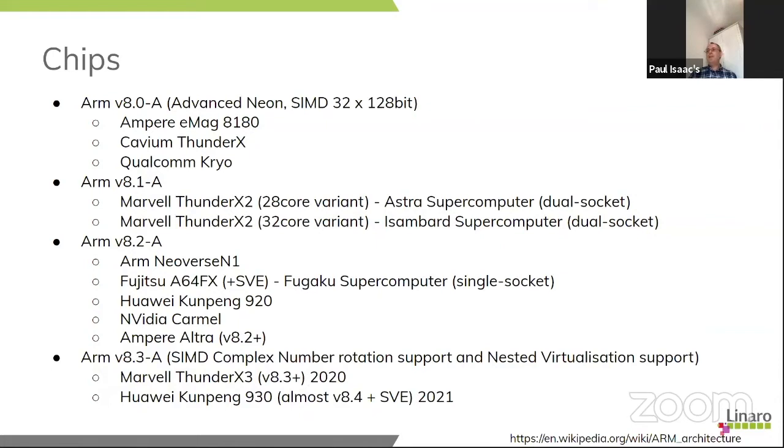So we're just seeing early deliveries of the A64FX from Fujitsu with the 8.2 ISA, but specifically the A64FX has the SVE extension. Now we potentially use SVE for larger SIMD functions. SIMD, hopefully not preaching to everybody, but single instruction, multiple data.